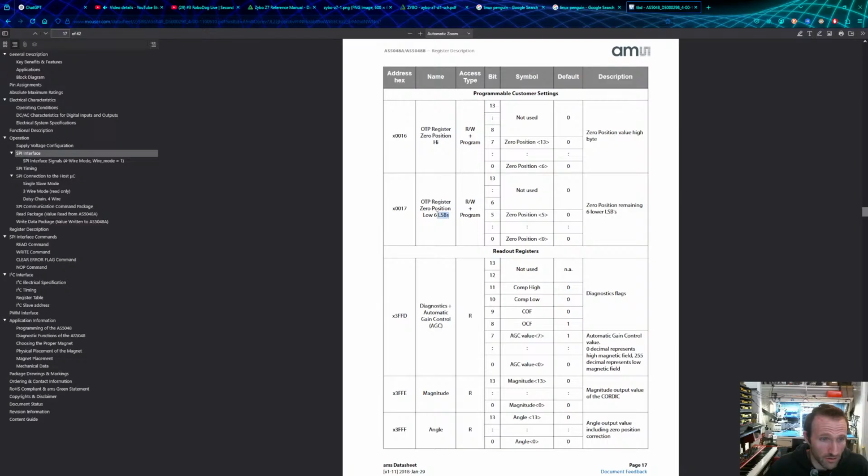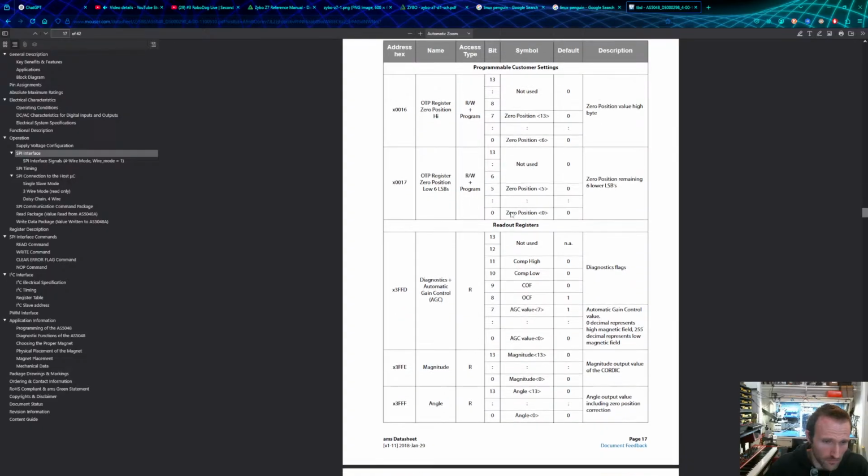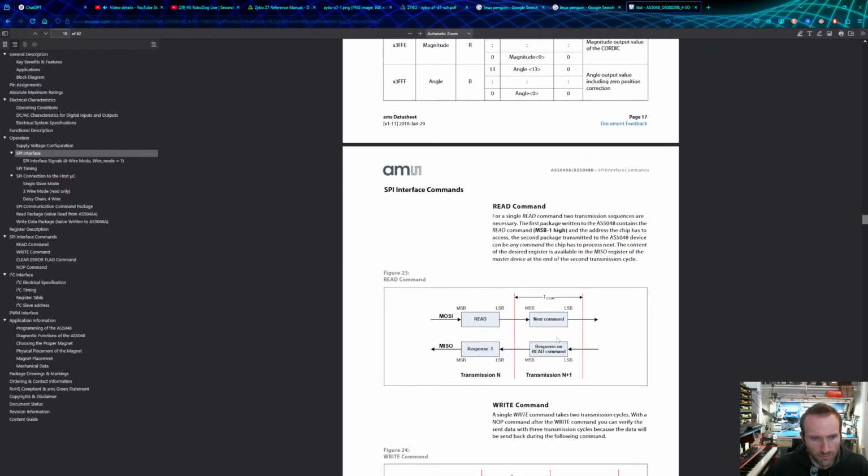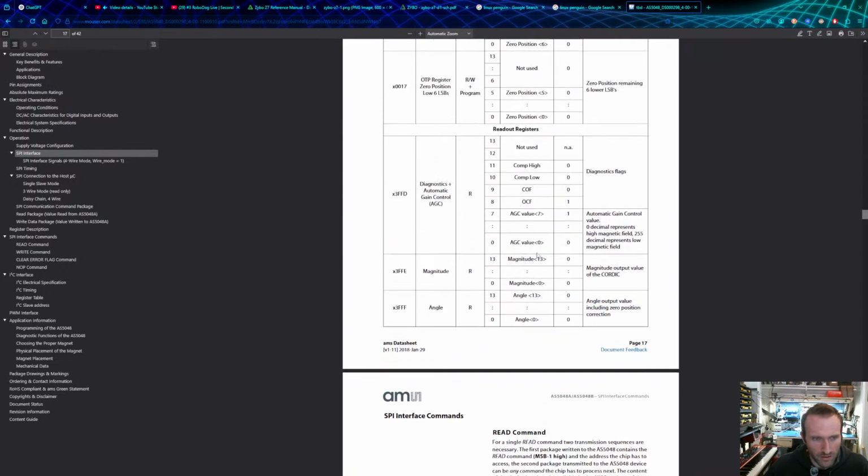So this is like lower significant bytes and then higher significant bytes. Sometimes when the memory spaces don't have enough, like if it's 16-bit and they want to go to 32-bit, they'll occupy 2 registers like this, just to get more resolution. If you don't know what that means, don't worry about it. We'll get there when we get there.